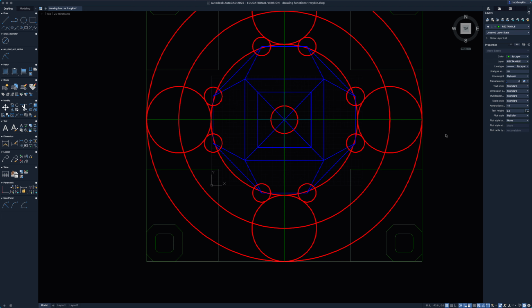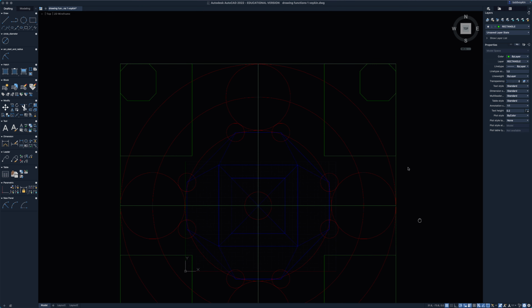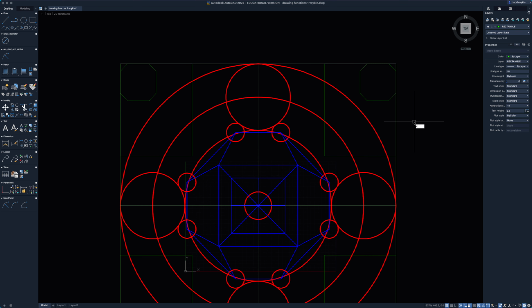Okay, so the next command says that we want to do the same thing in the top two little octagon-y, rectangle-y type things that we just created there, except this time we're going to create it with a radius of 25 and still with side lengths of 50. So I'm going to go back into my rectangle command, down arrow, oops, sorry, I gotta click in there, down arrow, and choose fillet again, and I'm going to change it from that 10 to 25. And now I'm going to again just sort of create that rectangle right there with side lengths of 50, comma 50.